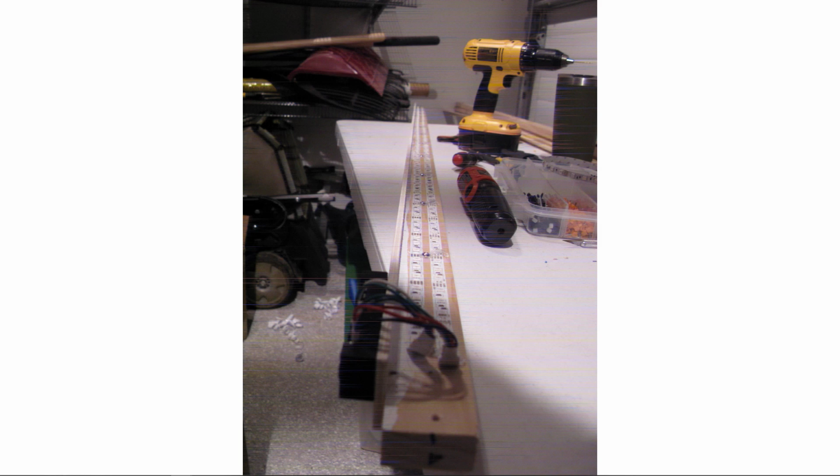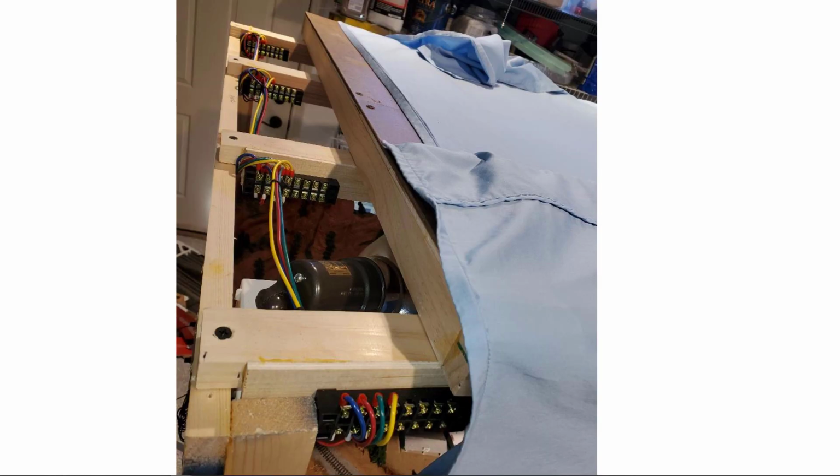Okay, now you can see the full length. So if you look at the red, green, blue, and common white wire, they bring in plus V, and then each strip is powered equally. In other words, I'm applying the same voltage at both ends of these two strips. Whereas if I had only applied the voltage to one strip at this end and then connected them together at the other end, then there would have been less and less voltage available as you go down through the length of the LED strip. Okay, so now I've got them attached to my dust frame on the layout.